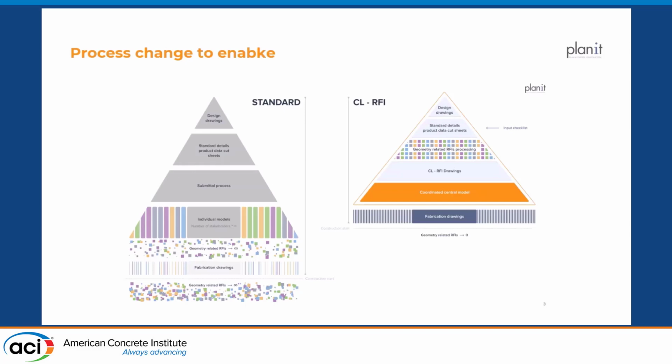We include construction tolerances and any type of code requirements that typically need to get checked at the end one more time, which is ADA, egress and exit, and all those things. So we do this in a very organized way. And then we create one centralized file that is actually the fully coordinated file. And then with parametric detailing, we actually extract all the fabrication drawings. That is why we don't need the RFIs in the field afterwards, or very, very few of them.